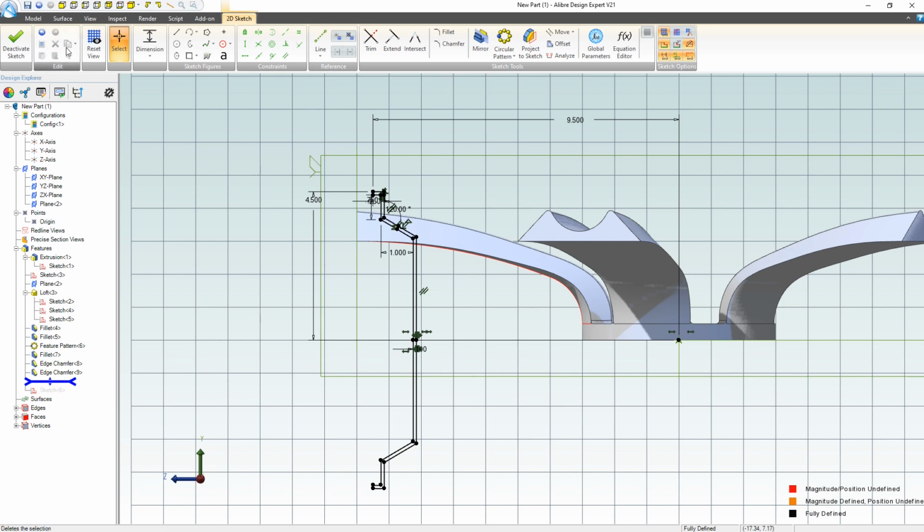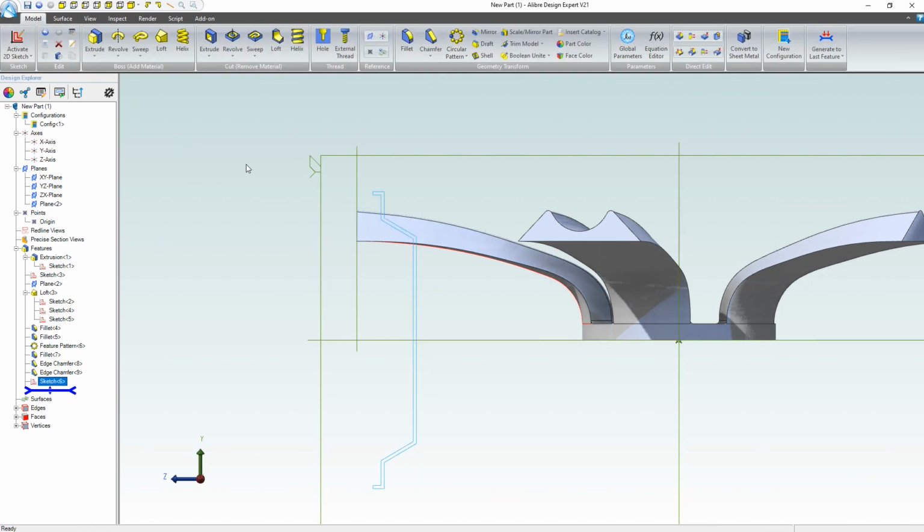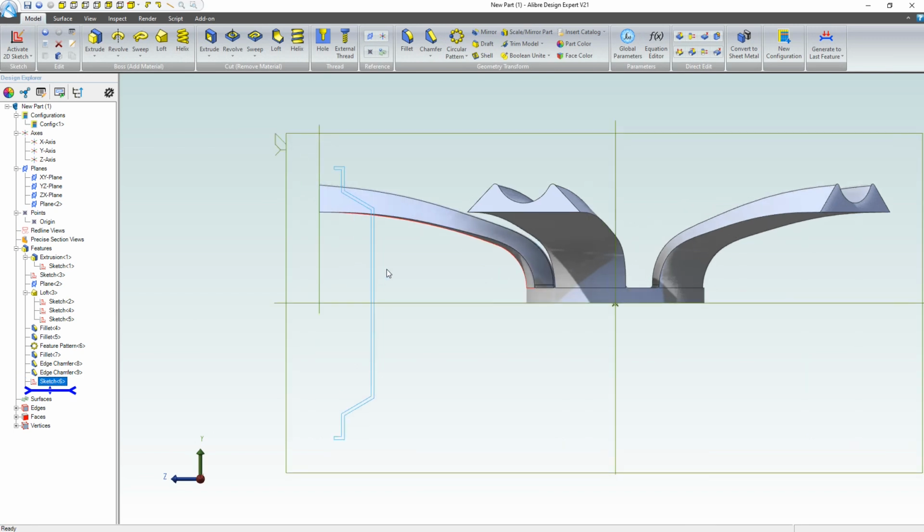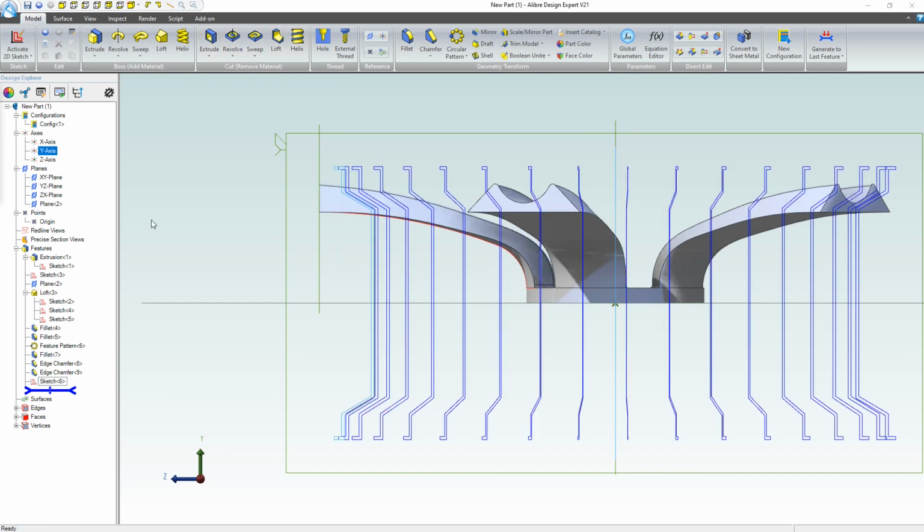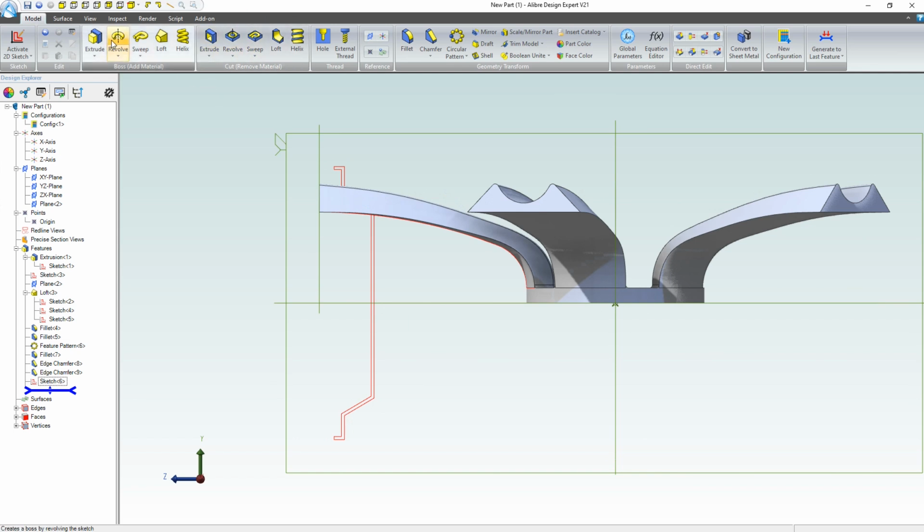I want now to go with, and like in CAD, there's a number of ways to do this. This is day 1 for me, and there's probably a way that you can do a revolved cut, delete the body, do another revolved cut, or do another revolve, and this time adding material. I don't know if I want to figure that out on camera and bore everybody to death, so I'm just going to do a revolve cut here. No, you know what? Actually, let's do an additive revolve. I think that'll be a faster route to get to where we're going.